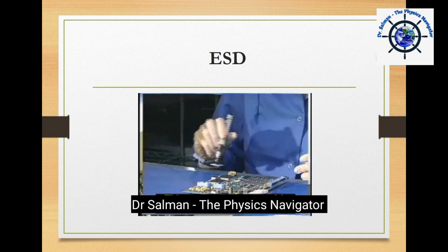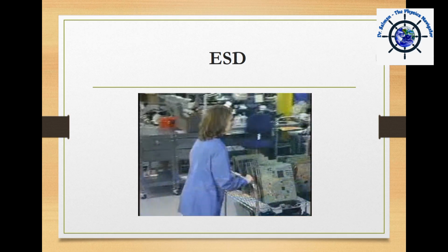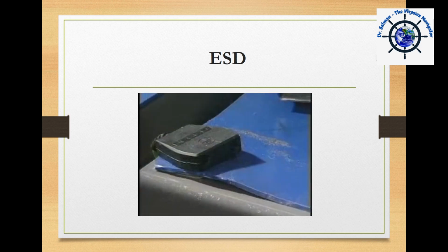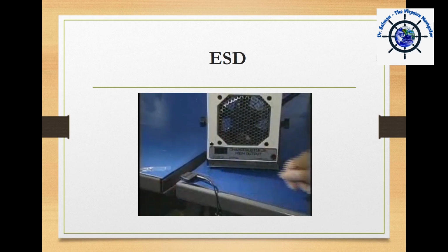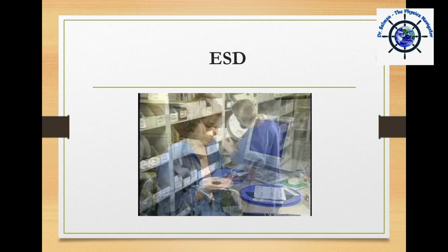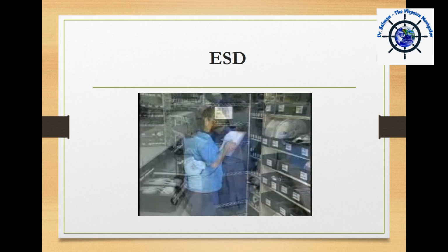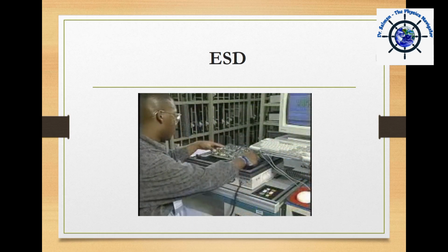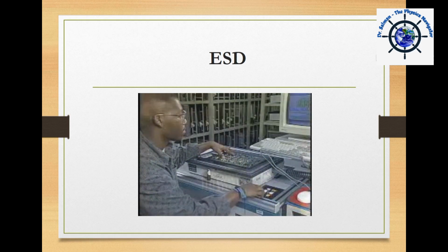Our last section deals with protecting ESD-sensitive devices during handling and when we transport them from one ESD-safe area to another. We've already learned how to protect these devices from the static fields and uncontrolled discharges in the work area. Whether you're performing incoming inspection, storing items in the stockroom, kitting, doing assembly operations, or testing and troubleshooting, here are some tips for the safe handling of ESD-sensitive devices.